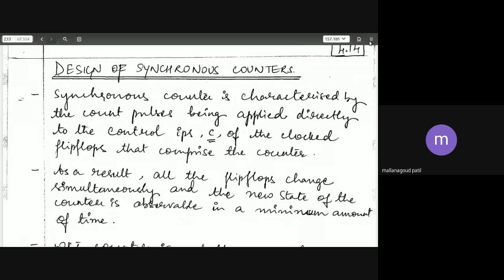To avoid that, what should we do? We have to change the pulse time. The pulse time has to be matched with the delay required to process the hardware you have designed. That is one case. The second one is you can change the concept of JK: from JK you have to go to master-slave JK. So these are the only two methods you can use.